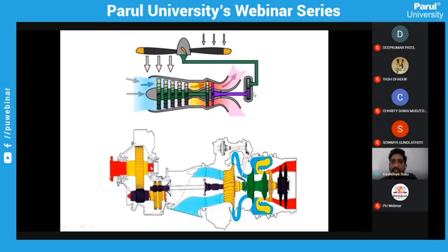At the end, the shaft is extended into the gearbox and then connected to a fan or a rotary part, anything which you require. Here it is connected to a fan like a helicopter, but in an APU you will just have the shaft till here only, the blue shaft. It will be connected to the generator from there. From there it will be giving electric power to the entire aircraft during the starting of the engine.